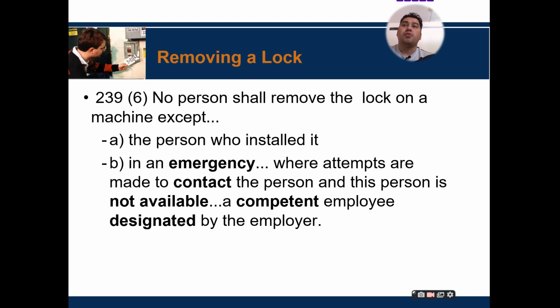Now, removing a lock. Once you have completed your maintenance work on the machine or equipment, after that you have to remove the lock. Before you remove a lock, you have to make sure that no other person shall remove the lock from the machine except the person who installed it. Only the person who installed the lock should remove the lock.